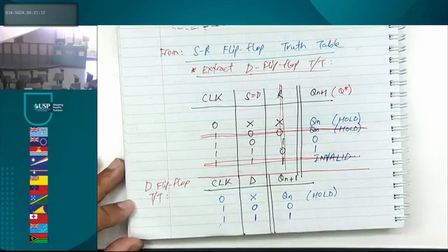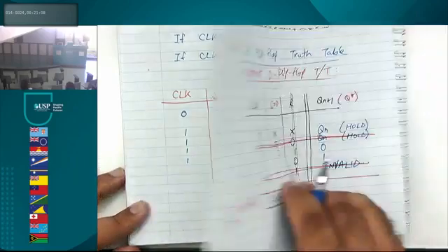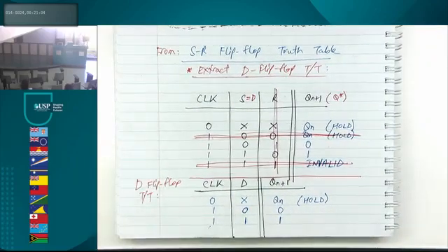Bang, done. What do you call this, guys? This would be called set and reset, but we don't use that word. So D is known as the data latch. Can you see it's a much neater, much nicer thing to do? Much neater, much smaller flip-flop. So that's the D flip-flop.